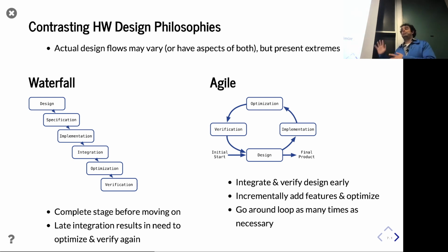That's what we dream for OpenROAD, but we aren't there yet. But this is definitely an aspirational slide of, let's get it more automated, more iterative, get more feedback. And even if it's not perfect, for example, let's say you have an ASIC design and you push this through a flow, and because you aren't there manually fixing it, you have DRC errors, right? Those are things that say you can't actually make the chip. Even those DRC errors, if you fix them, how much is that going to change performance? There's only a couple small DRC errors. It's not going to change performance very much, right? And so you still learn something from running through a flow in spite of those DRC errors.